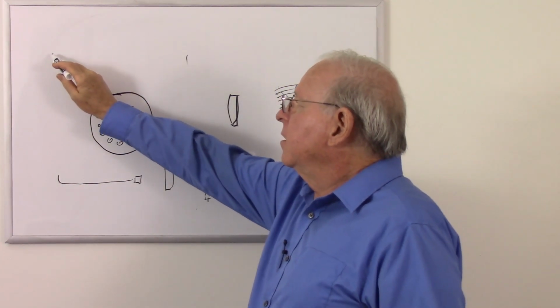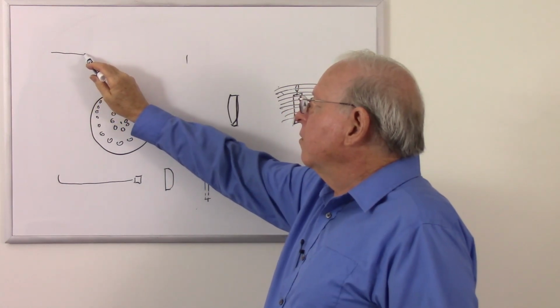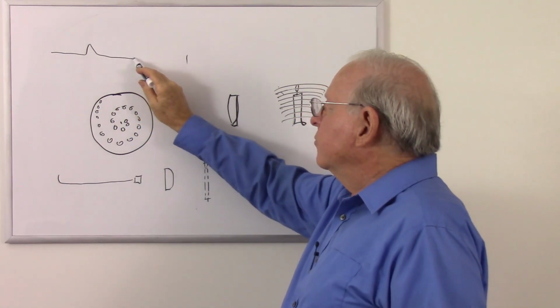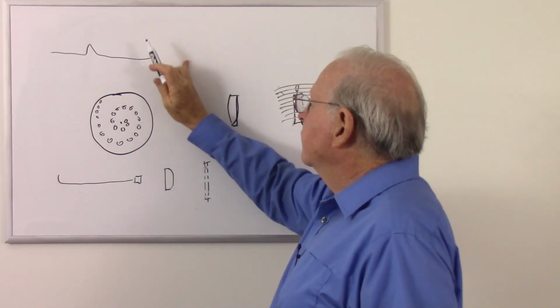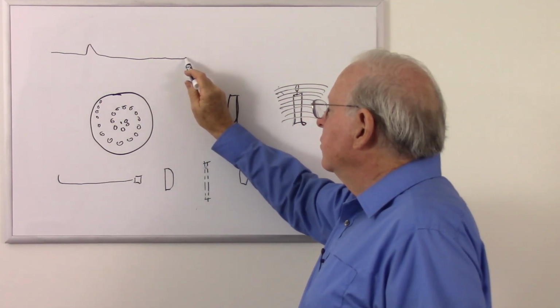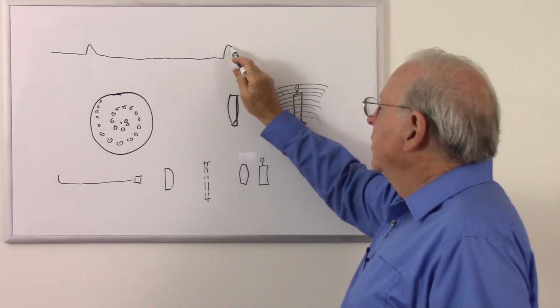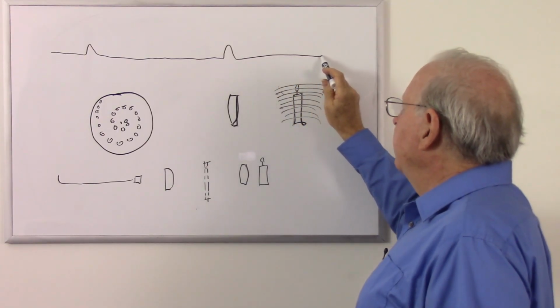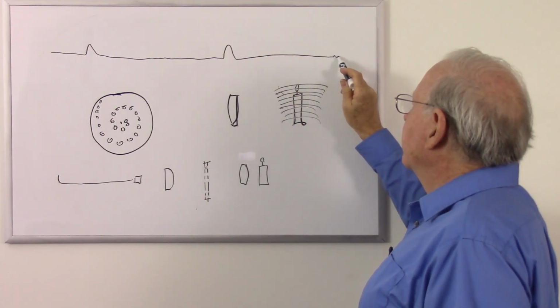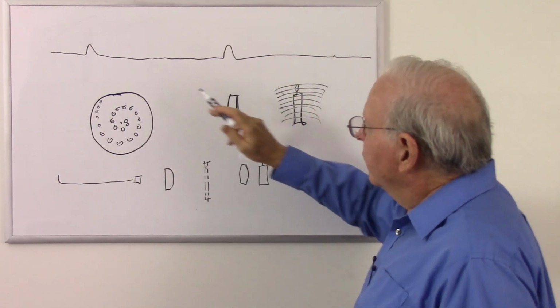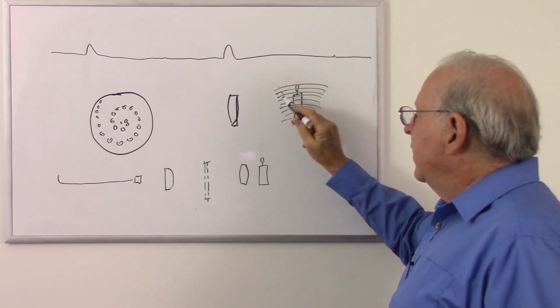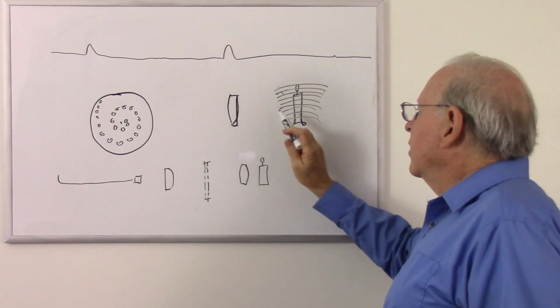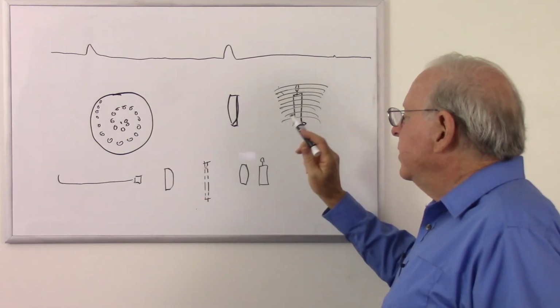It's going to be low voltage, low voltage, low voltage, goes up and then down as it goes across the flame. And we're going to get the same thing with the next one. We'll get low voltage, then bright as it goes across the flame, and then maybe a little bit as it goes across the wick. And so we get this long string of information that is these scan lines, if you will, put together.